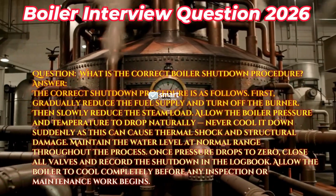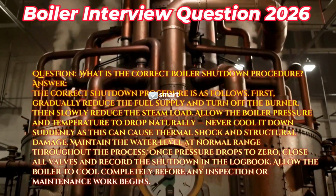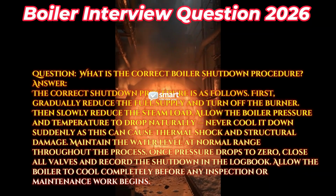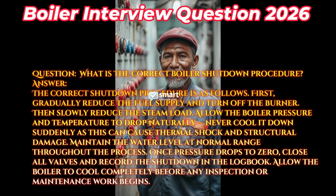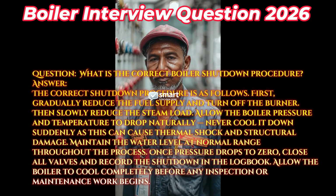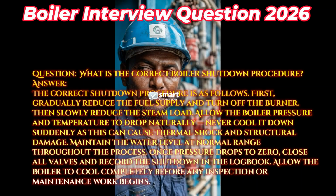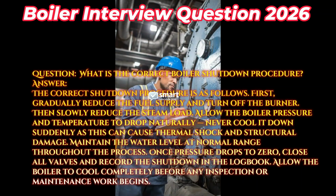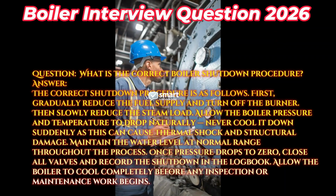Question: What is the correct boiler shutdown procedure? Answer: The correct shutdown procedure is as follows. First, gradually reduce the fuel supply and turn off the burner. Then slowly reduce the steam load. Allow the boiler pressure and temperature to drop naturally. Never cool it down suddenly as this can cause thermal shock and structural damage.